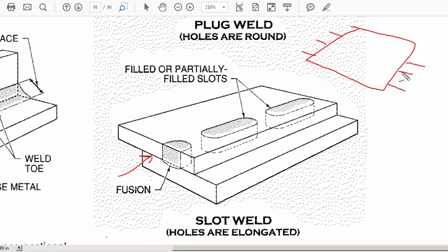And these sheets are laid down, but how do you connect the sheets to the metal below, the metal joists? What they'll do is they'll basically do plug welds, where they'll go along every so often and penetrate to create a weld component between the joist below, and here I'll just draw the joist out there, there you go, the joist below and the metal sheet above. And they'll actually do it on certain sizes and pitches, and we'll talk about what that is a bit later on. But there's your concept.